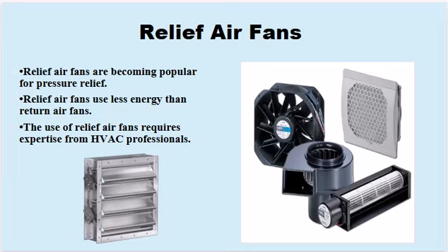Firstly, these fans operate when the HVAC system generates too much air pressure, helping to balance the system and maintain proper operation. They consume significantly less energy compared to return air fans because they only operate when there's excess pressure to manage. Additionally, relief air fans ensure that the HVAC system maintains optimal performance without unnecessary energy use.